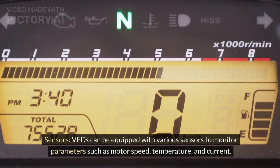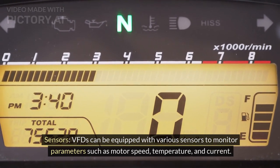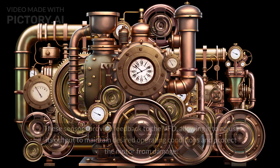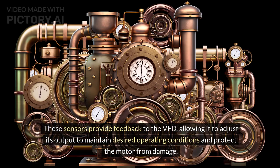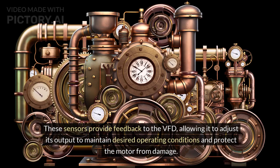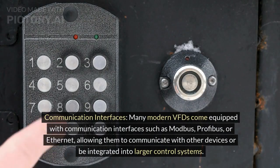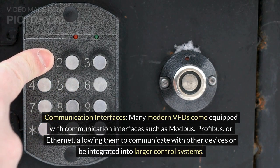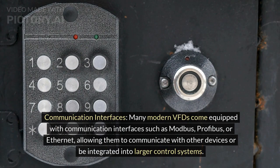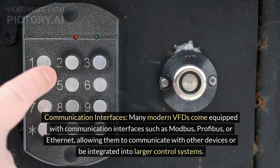Sensors. VFDs can be equipped with various sensors to monitor parameters such as motor speed, temperature, and current. These sensors provide feedback to the VFD, allowing it to adjust its output to maintain desired operating conditions and protect the motor from damage. Communication interfaces. Many modern VFDs come equipped with communication interfaces such as Modbus, Profibus, or Ethernet, allowing them to communicate with other devices or be integrated into larger control systems.